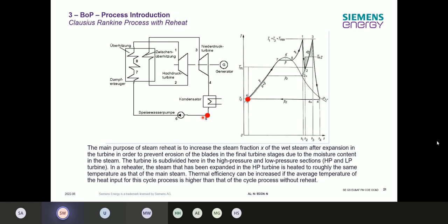Second step is now we have the feed water pumps, or condensate extraction pumps, and then the feed water pumps to increase the system pressure. That's our one-time system pressure increasing. The next step is then the preheating through the economizer. So there our temperature will be increased.